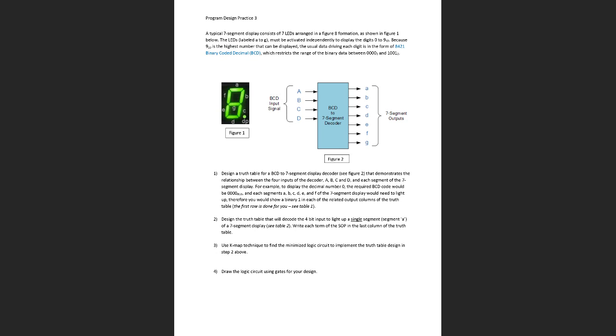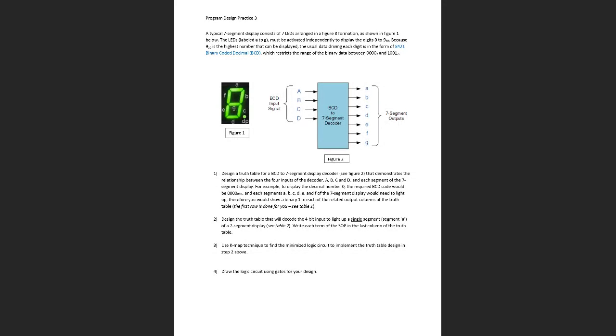And what you have over here is an actual integrated circuit, an IC chip. It takes this BCD to 7-segment decoder to operate this 7-segment display. Well, how does a 7-segment display work? As I said before, you can display the digits 0 through 9, and what you would do is put in BCD. Now you've got to remember what that is. Anybody remember what BCD is? What do the B, the C, and the D stand for?